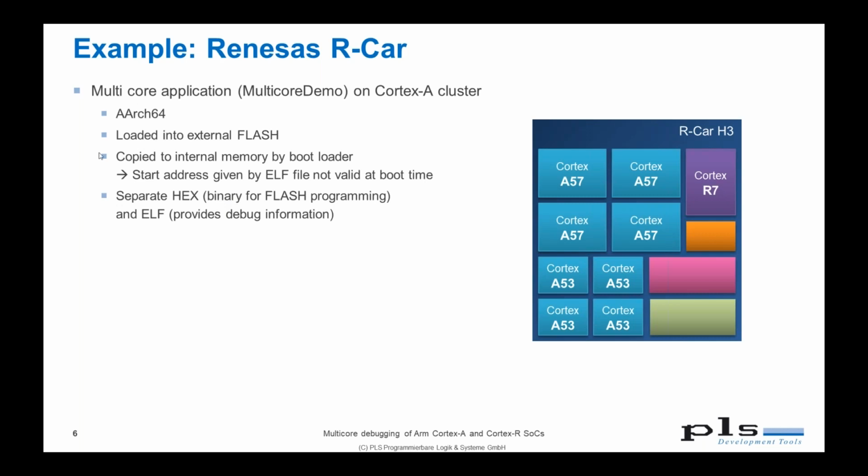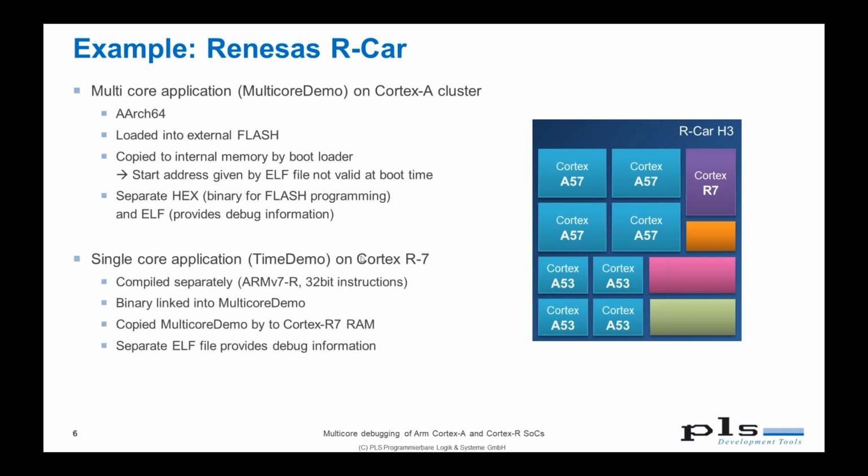The application itself is compiled into a hex file and a separate ELF file. The hex file provides only the binary for flash programming, and the ELF file only provides debug information. So you need both files for debugging this device.